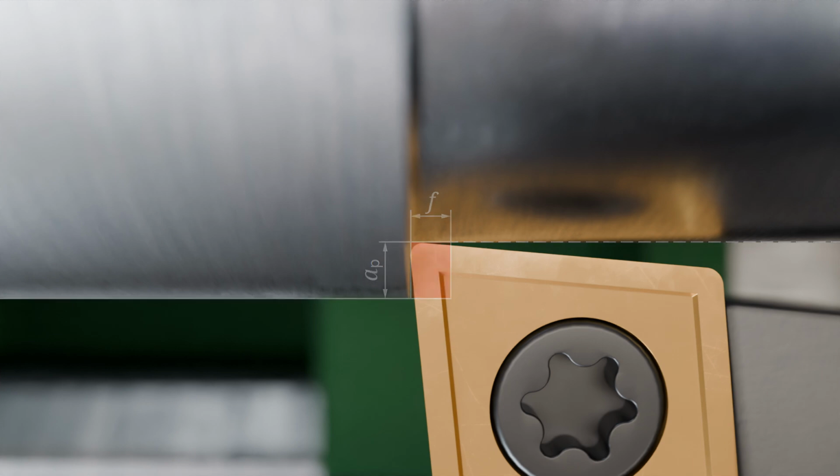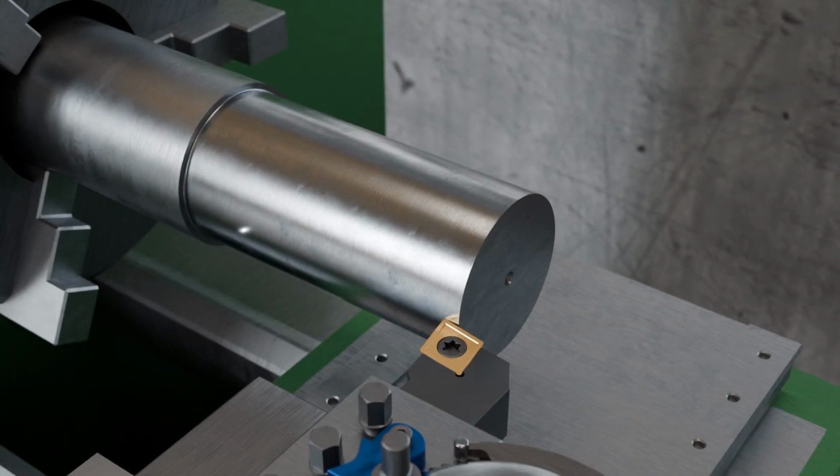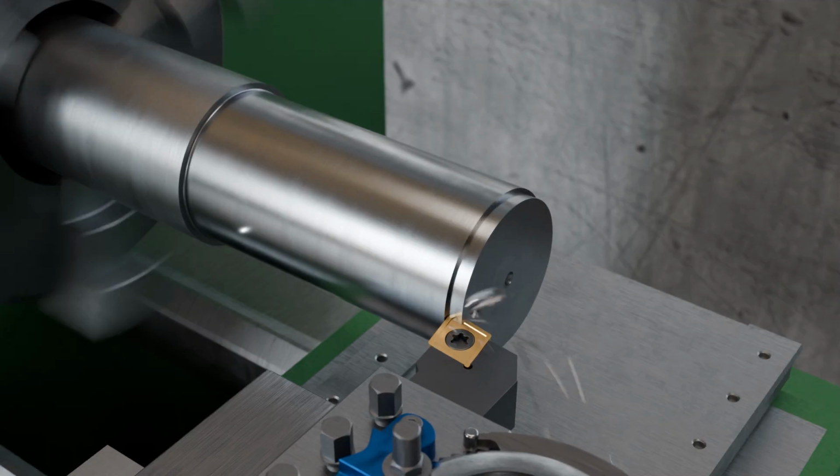In the following, the different turning methods will be examined in more detail. In the case shown so far, a cylindrical surface was produced by longitudinal turning. With the present indexable insert and the chosen approach angle, it is also basically possible to machine the face of the workpiece flat. The feed moves perpendicular to the axis of rotation.